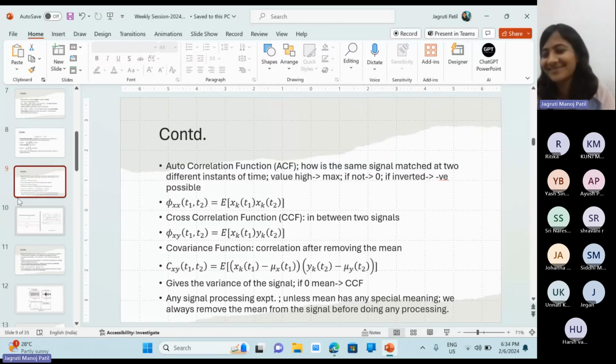Convolution. Yes. In convolution, you take a signal, you delay it, or you entirely flip it if there's no delay given, and then you multiply both of them. So here the role of sign takes place: you invert the entire signal. But in autocorrelation, the sign goes off. You directly multiply: if it's autocorrelation, the same signal; if it's cross correlation, two different signals at two different instants of time, or perhaps the same instant of time.